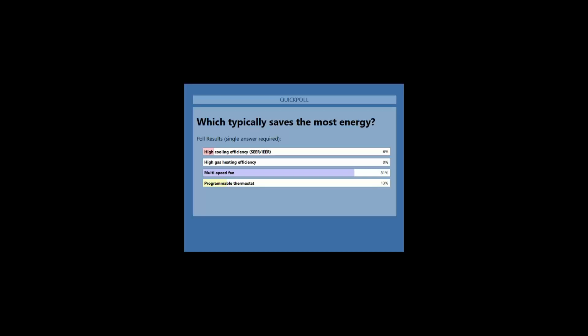You can also get a compressor that can unload itself, a digital scroll compressor. Scroll compressors are what most of you have in your units, but you can get one that unloads itself internally. And we don't have time to dive into that today either. Just know that it can run at less and less capacity. And most of these modulate from 10 to 100%. So just pretend for right now, each percent is a stage. You got 90 stages of capacity essentially, instead of 1 or 2. So you got really good control in this case, and a lot of energy savings can be had.